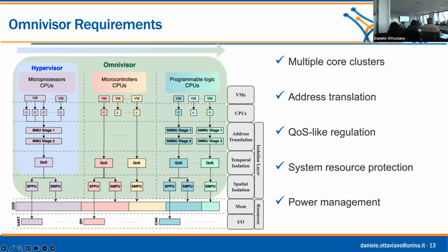Exactly in that line, are we assuming all the VMs are being well behaved at least? No, we are not assuming that. For example, from the FPGA, you can fake that you have the highest privilege by playing with AXI bits and then change all the QoSs, right? So who prevents that? Basically, you can use the system memory protection unit and some memory and peripheral protection units to avoid this kind of behavior, because these protection units are placed near the resource to protect.